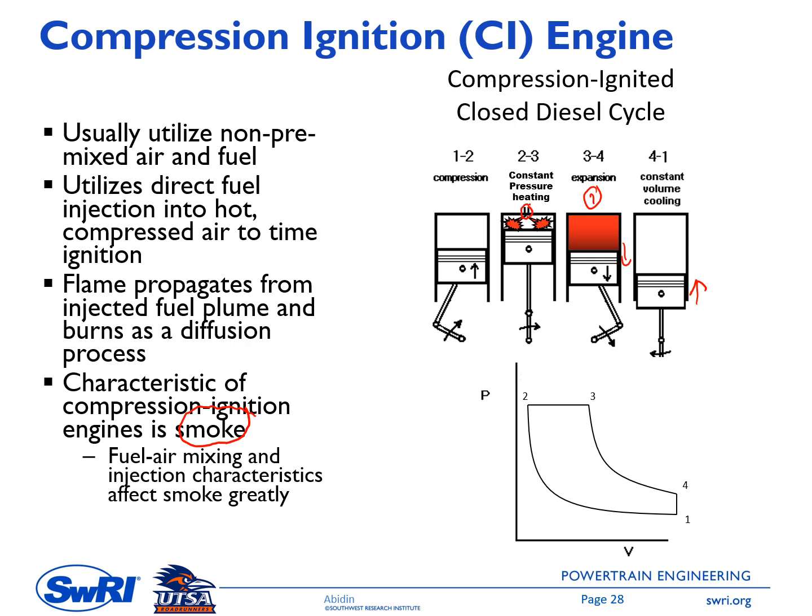has a better efficiency because of higher compression ratio. And you know in thermo 1 that higher compression ratio also means better engine efficiency. And this compression ratio is limited by the strength of the material, which is the material for the piston, cylinder head, and liner.